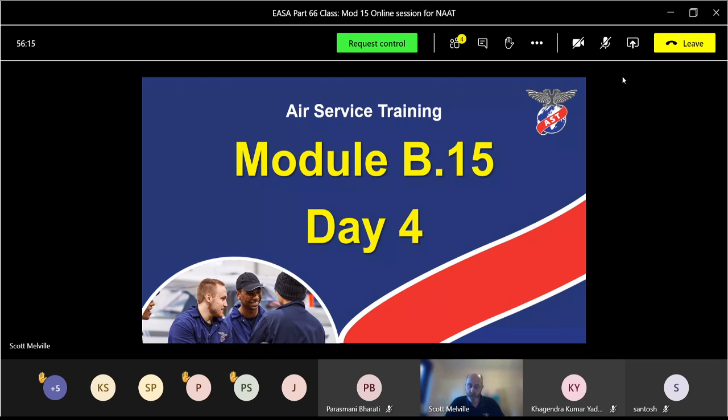So we've got the pressure drop control diaphragm, we've got the evacuated capsule, which is P0, and we've got the open capsule P1, all controlling the bleed valve, the spill valve. What other type of component will operate a spill valve? And it will operate on two options. So what else can operate a spill valve? I'll give you clues to do with electric.